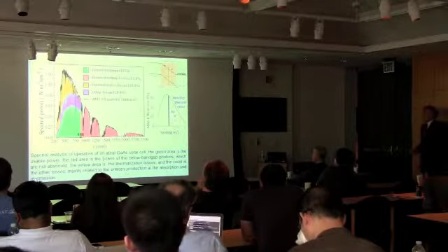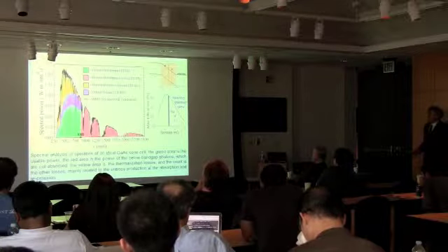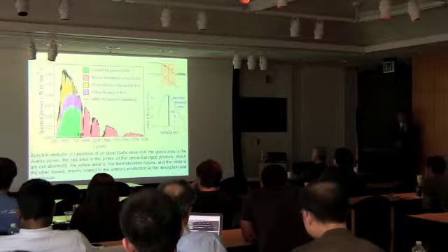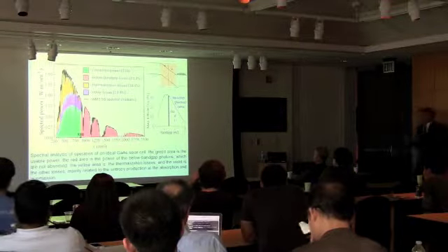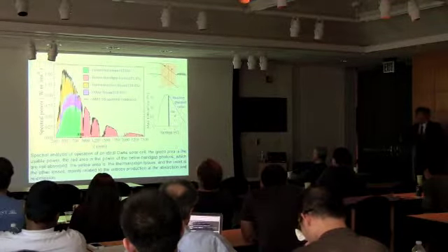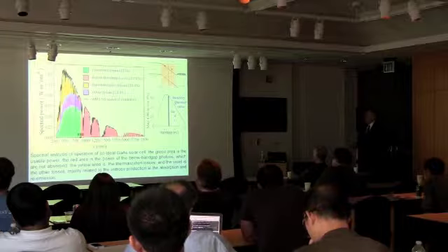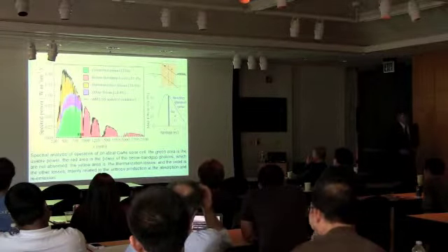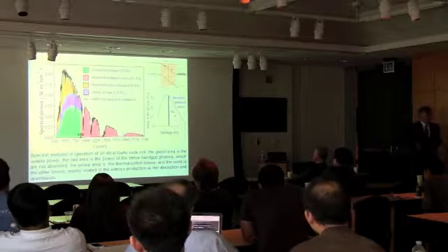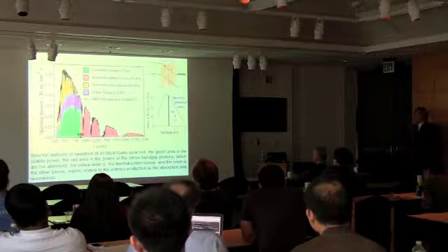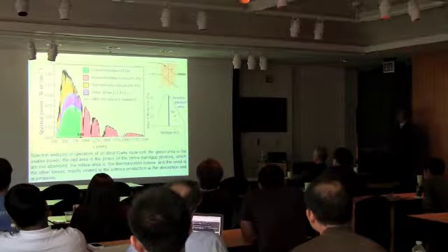And that is why there are some other losses that in principle you can struggle a little bit to improve. So for each semiconductor you will have a certain maximum possible efficiency that is drawn here, and for gallium arsenide, the theoretical efficiency is about 30%. So whatever you do, you cannot have more than 30%. This is absolutely a limit, and each material has its own limit.